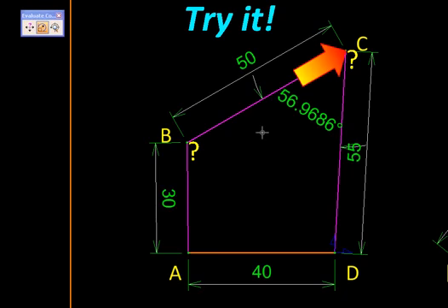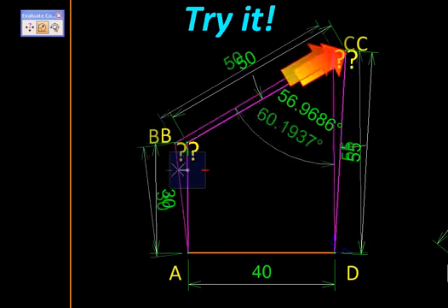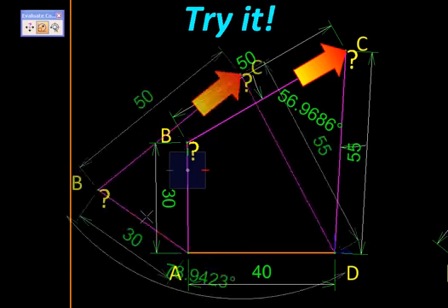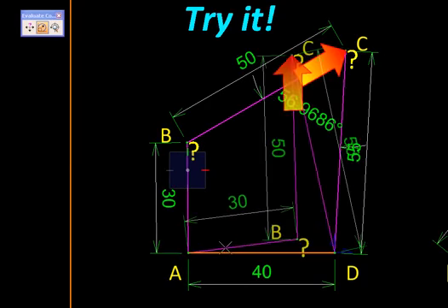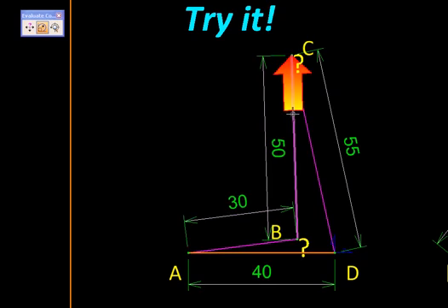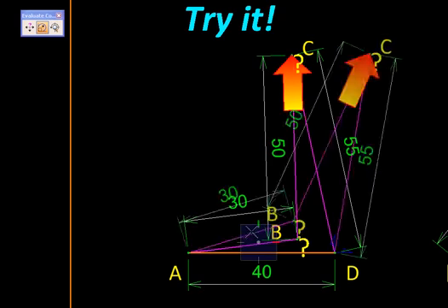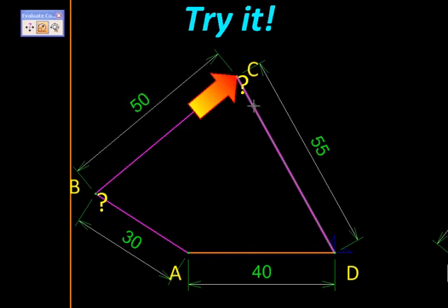To understand the concept of transmission angle, let us consider this output link as a door that we are trying to open or close, and the force in the coupler which gets applied to the output link as the force we are applying to open or close that door. Then as the mechanism moves, the angle between the force and the door changes. Now think of which is the best way of applying this force. Is this a good way of opening a door, or is this a better way of doing that?